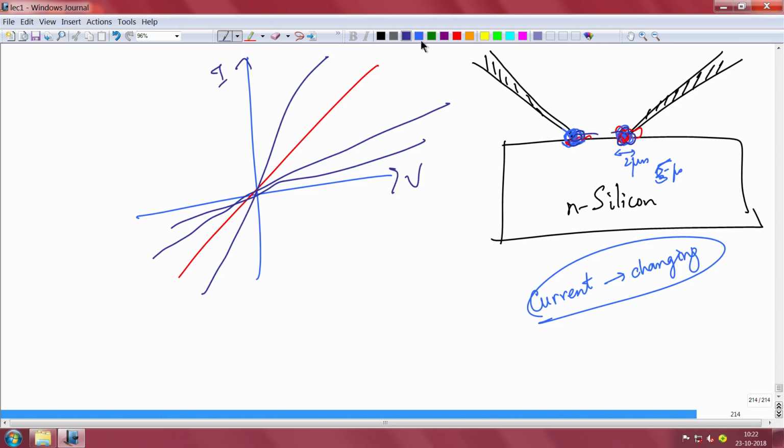And besides, there is moisture, there is all kinds of atmospheric stuff that will contaminate the surface, and this surface will keep modifying as the atmospheric condition keeps changing. The humidity, the dirt, the flow of the air, everything will keep changing. These are very sensitive devices. A transistor, a device is very sensitive. So all these will modify the surface here, all this will modify the contact area, okay. It will modify the area at which the probe tip is contacting your surface, and that will keep making the IV keep changing. There is no consistency.